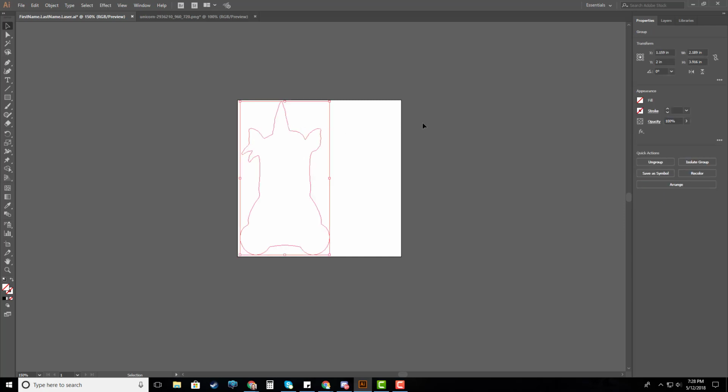Okay, so I'm going to click that and go ahead and change it to red. But remember, on your screen it needs to be RGB red. You can see that it's a really thick red outline, but we have to change that size, because remember, our constraints said that the size needs to be 0.001. That is not a choice option in here. You have to actually click in here and type in that number yourself.